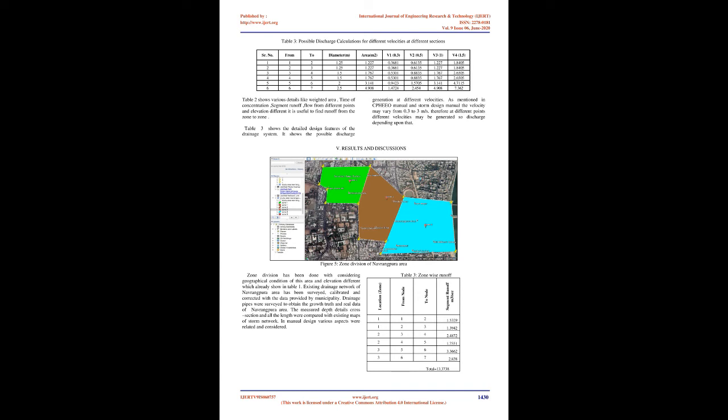Area of Navrangpura with Google Earth Pro. Take different pinpoints through the Pin tool, with various longitude and latitude mark points. After that, choose the Polygon tool and join all points to get the whole study area. After completion of joining points, we have various options like style, color, view, measurement, etc. Figure 3, Area Measurement in Google Earth Pro.